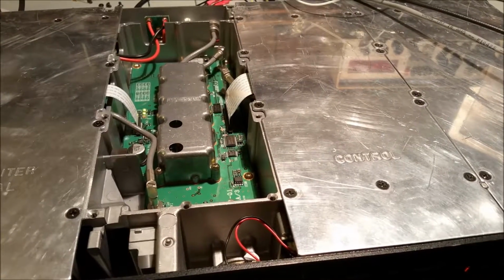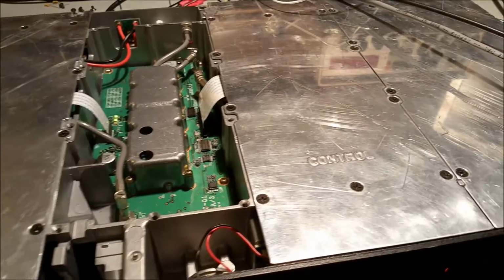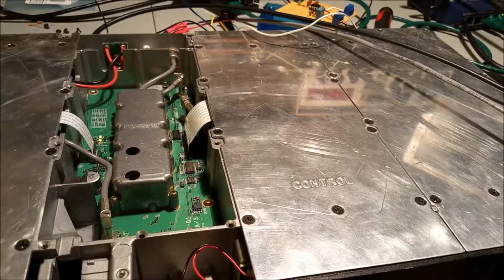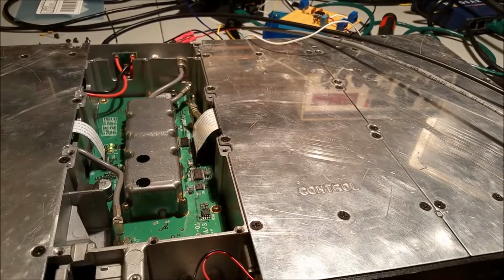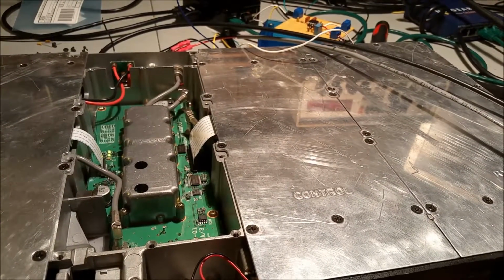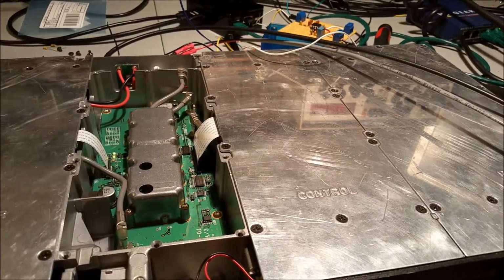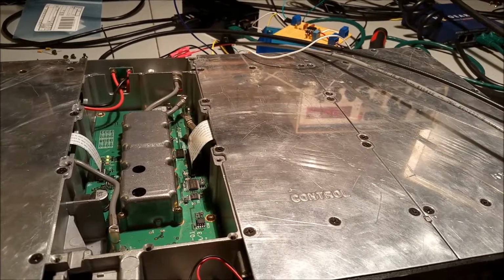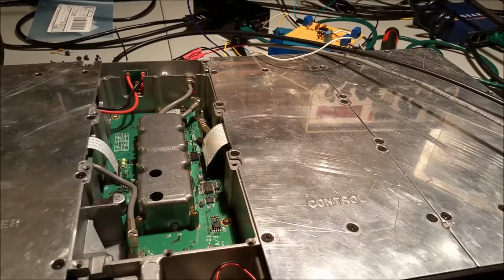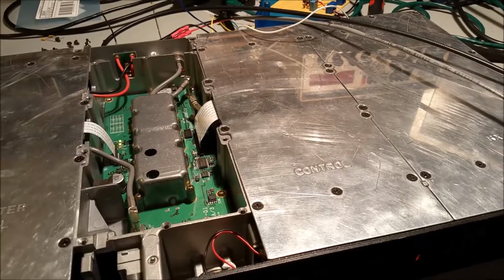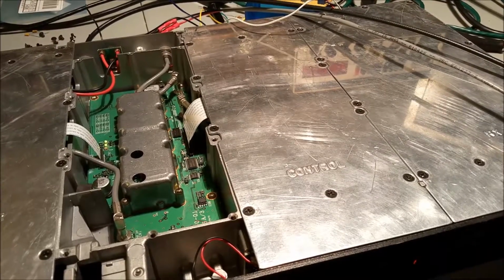I actually just got the RTCM to connect to the host the other day with the help of somebody on the AppRPT mailing list. And I also found out another piece of information, that the RTCM wants to see a 5-volt peak-to-peak, 1 pulse per second input, and not 3.3. Apparently 3.3 does not work. And my Chinese GPS DO only outputs a 3.3 volt signal, which was kind of a bother.